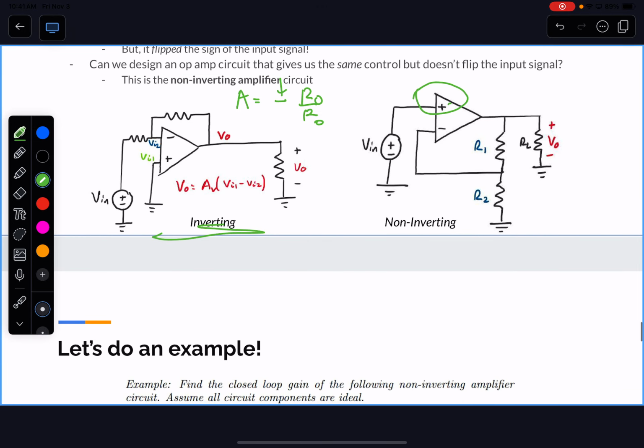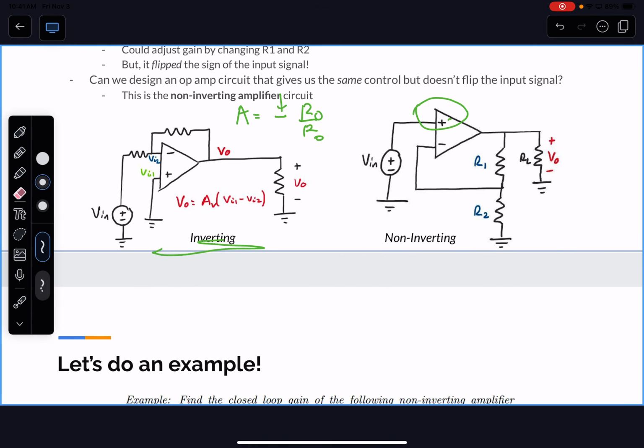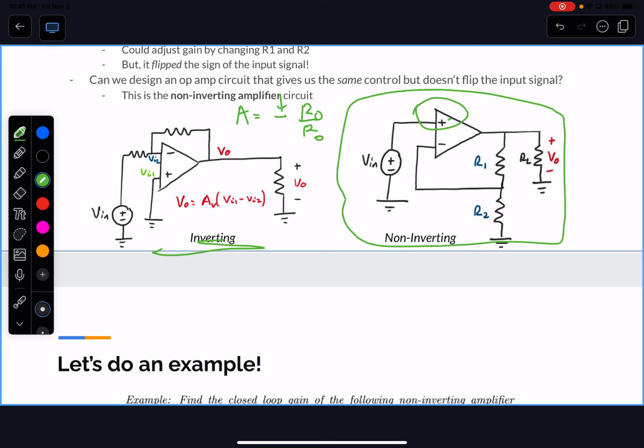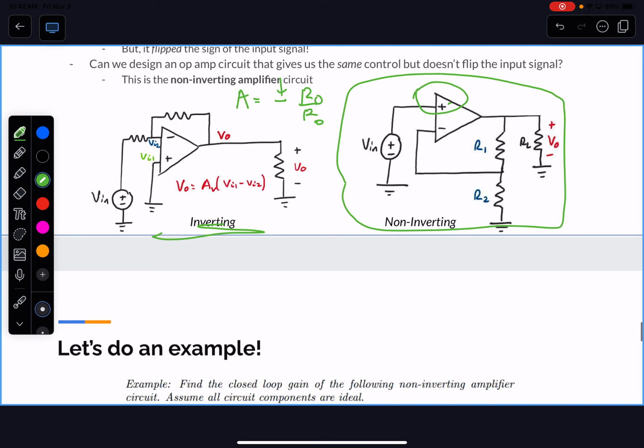And the way to do that is your circuit looks like this. And this is actually a lot of times the circuit I use, right? I want a non-inverting signal. I don't want it so that when I put in a signal to play notes, all of a sudden it starts playing the opposite things. I want whatever I'm putting in as control to be just an amplification of the exact same thing. I don't want to be pressing a button on my remote and then the TV amplifies an opposite action. I want the same action, which is why we use a non-inverting.